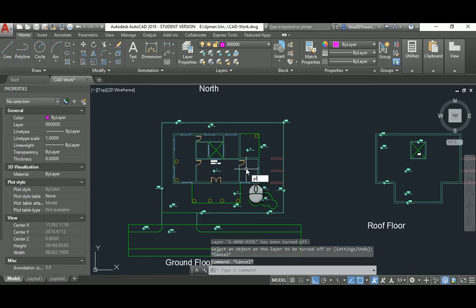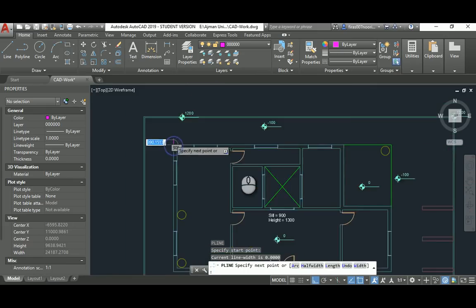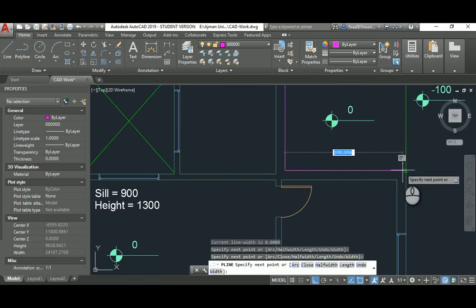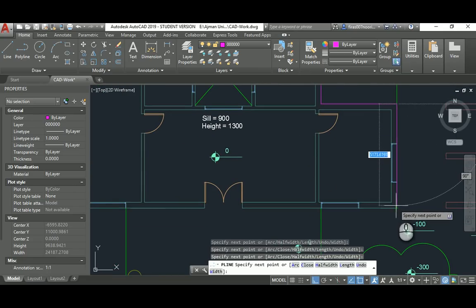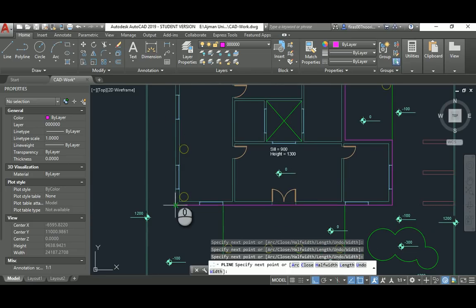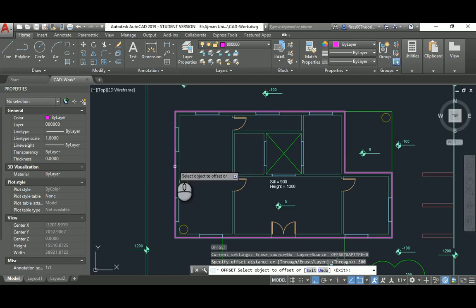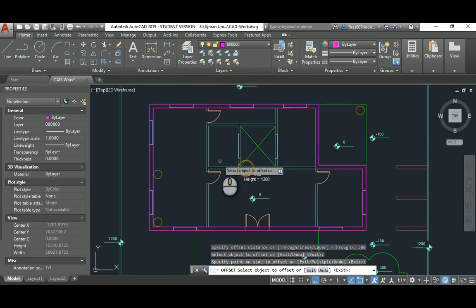Now hit polyline and quickly trace the walls, actually the external perimeter of the walls. Ignore any doors and windows. Offset that, I think 300, and you'll get this. If this were just a solid building with no core inside, you would just send this as a write block from AutoCAD to 3D Studio Max.